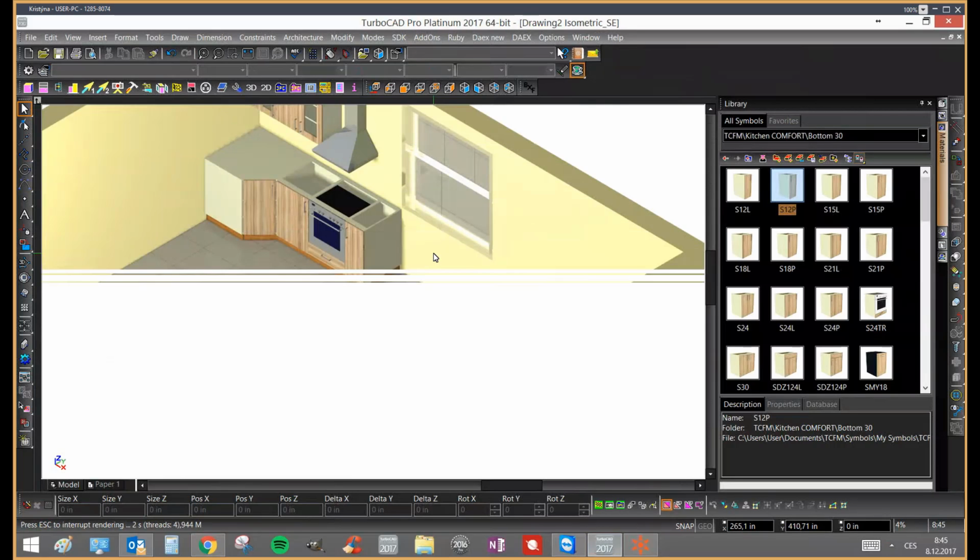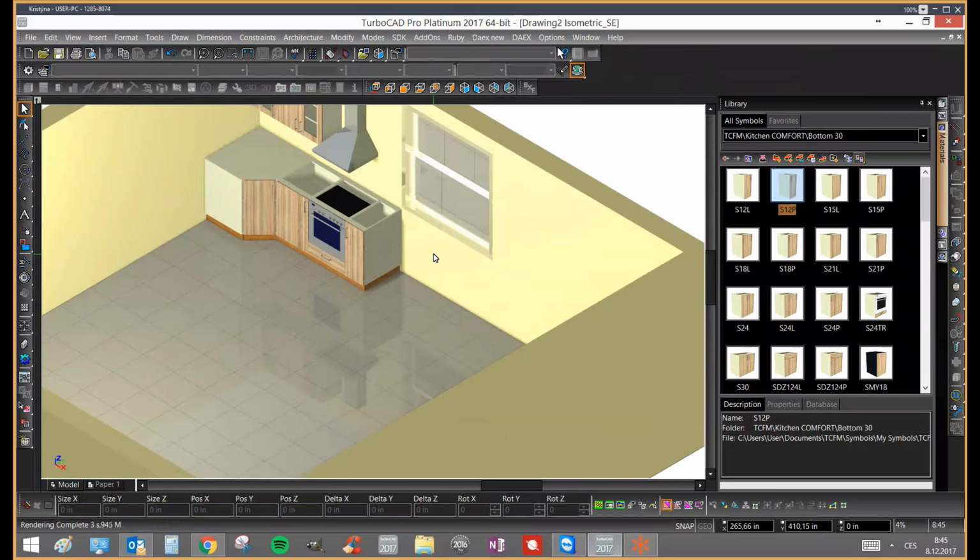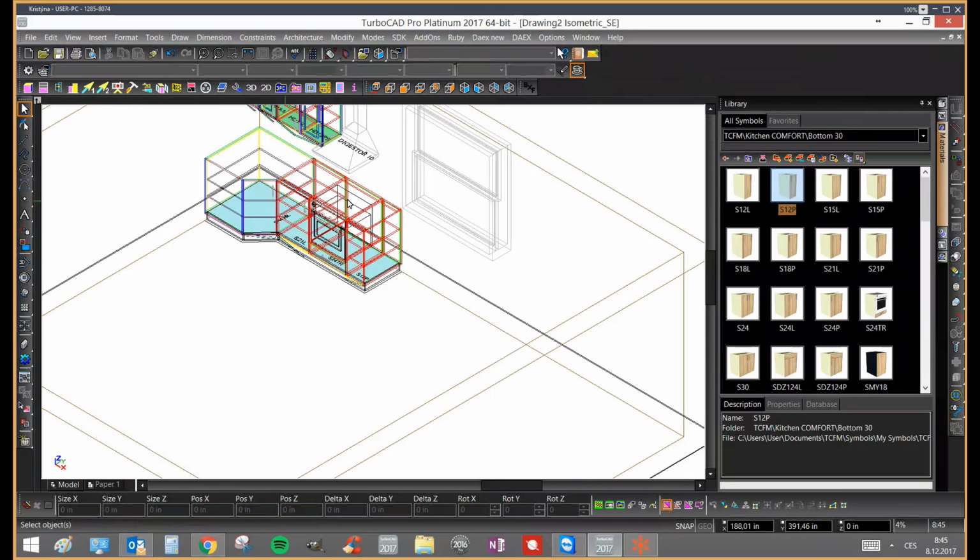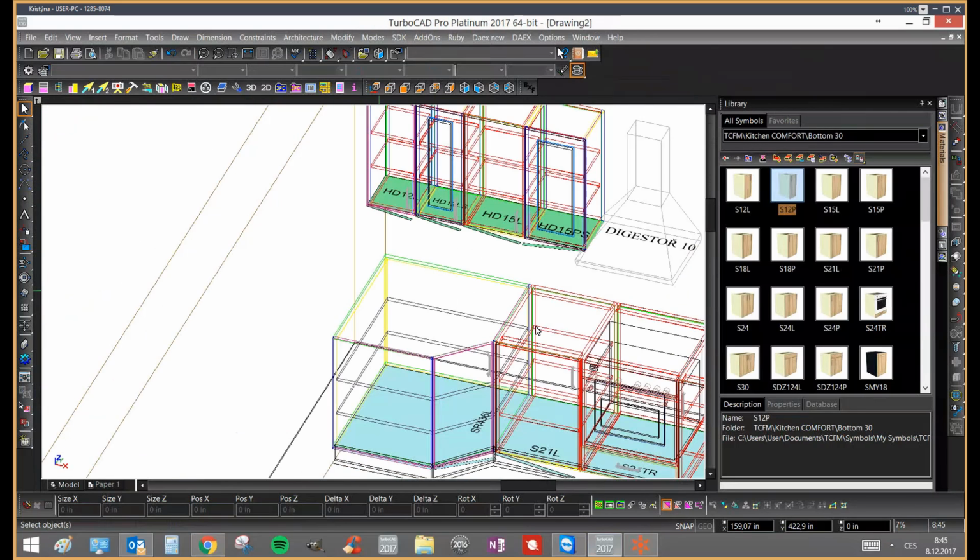Okay, then when you are putting a worktop on the cabinet, you can use auto work plane by face or by facet. Because you have to tell the program where to, of course, draw the line on the cabinet.